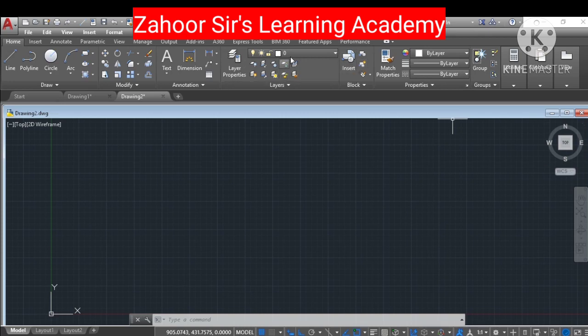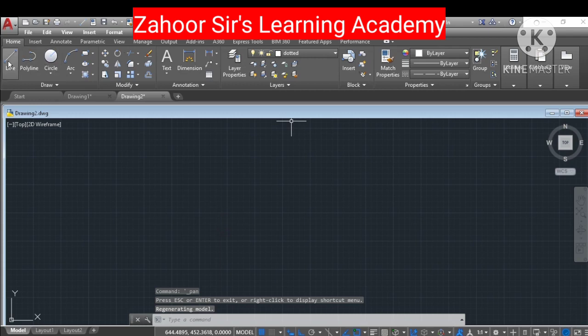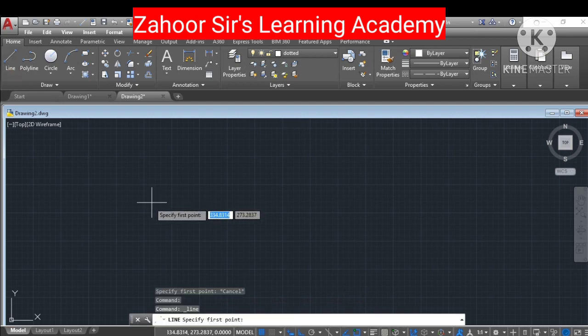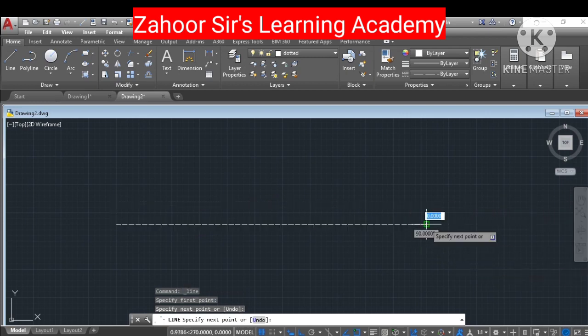Let's start drawing. First of all, we have to choose from the layer the dotted line. That dotted line will draw us the central line of the shaft. So I have taken it from the layer, and now I will go to the line command to pick a center line for my drawing. So this is my center line.